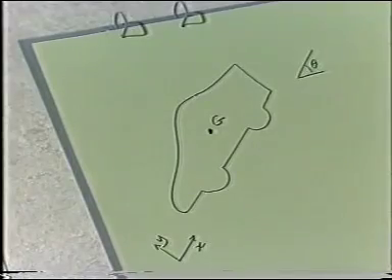The weight force acts at the centre of gravity by definition. For most engineering purposes, you can take the centre of gravity to be at the centre of mass. It's only in very specialised cases that you need to consider the difference, for example, for some satellite motions. So I'll put the weight force here, acting straight down, of course.